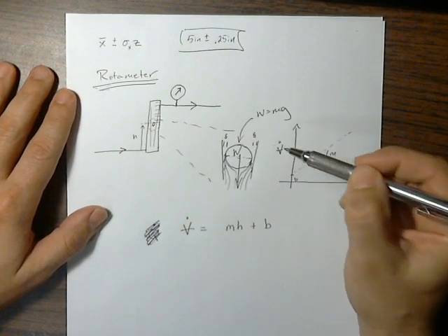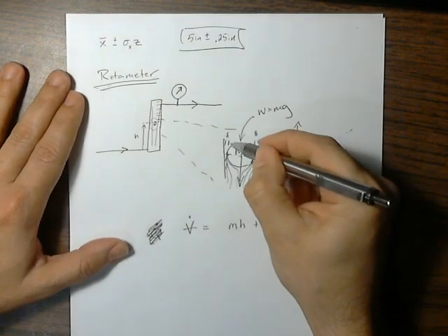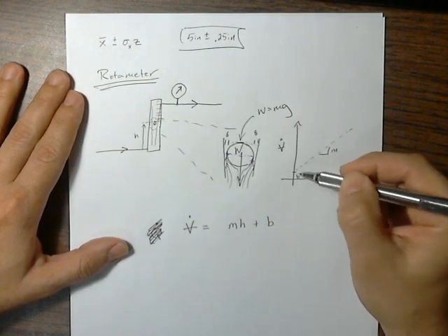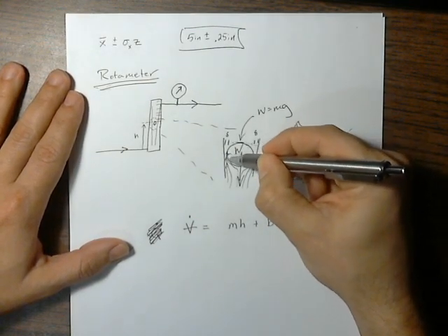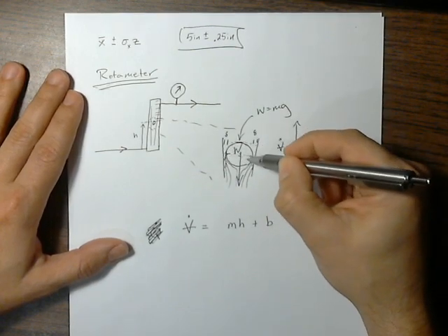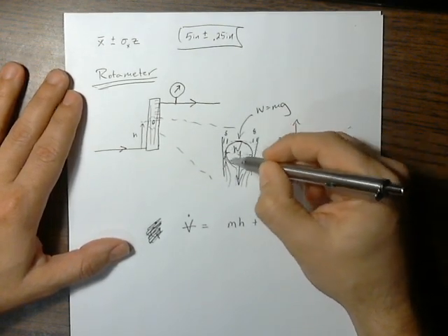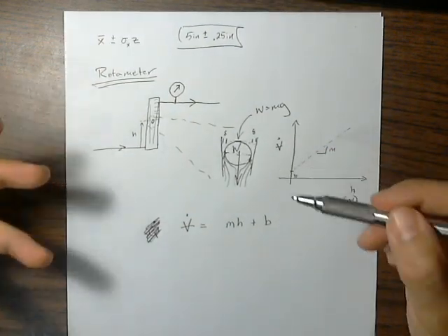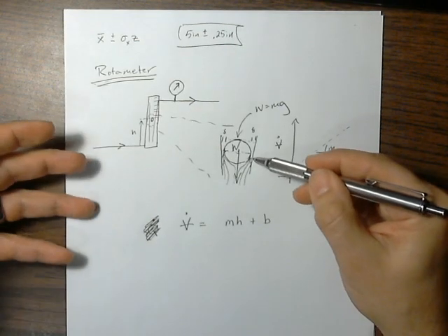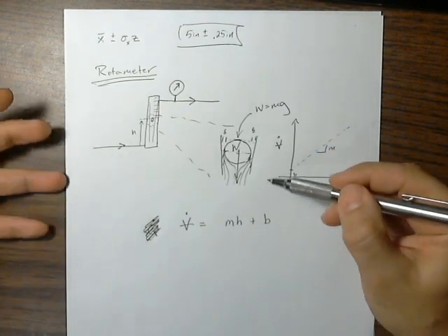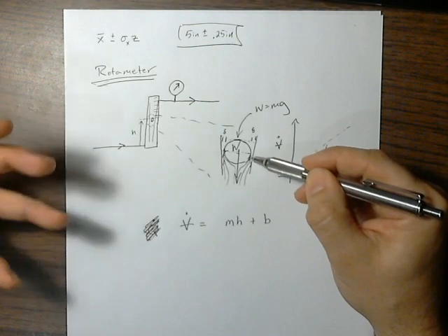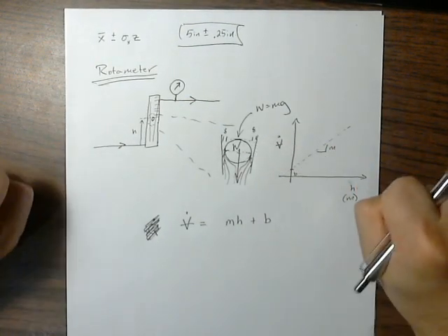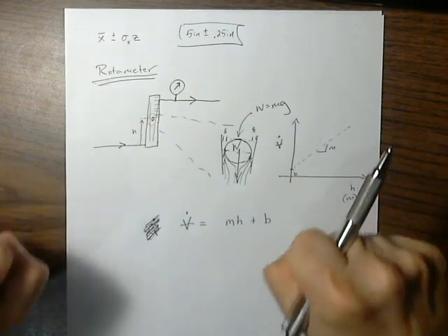The top of the ball is really easy to see. If I'm looking for a line that forms right on the top part of that ball, that is really easy to see. But the middle of the ball, I mean, you could squint and tilt your head and convince yourself that the middle of the ball is in this pretty wide range, right? That is the hardest part of the ball to read. It is the least reliable place to read. It is the hardest place to train an operator to reliably read. The top of the ball is absolutely the better place to read the ball.